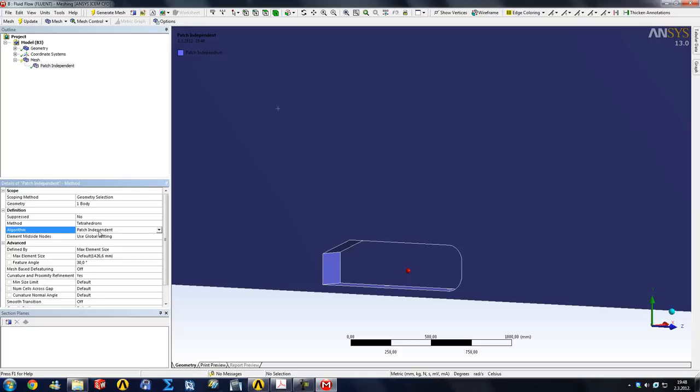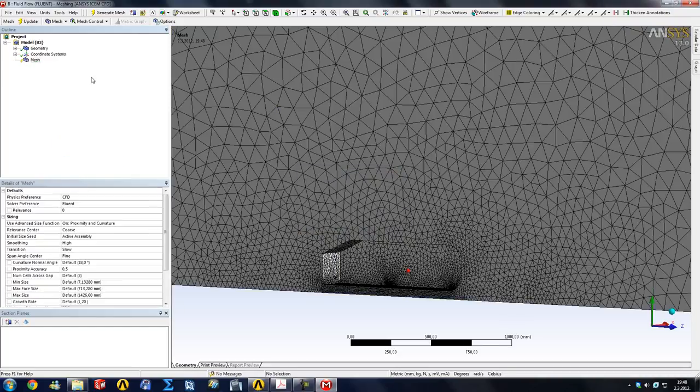This would do the mesh in the ICEM CFD algorithm for octree mesh, and then the slow transition and the fast transition would differ, and you can check online and in the help files how the fast transition looks. But the slow transition is more suited to CFD because it fills the volume with elements a bit more smoothly and more proficiently.